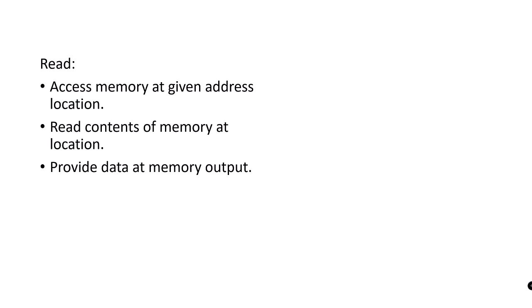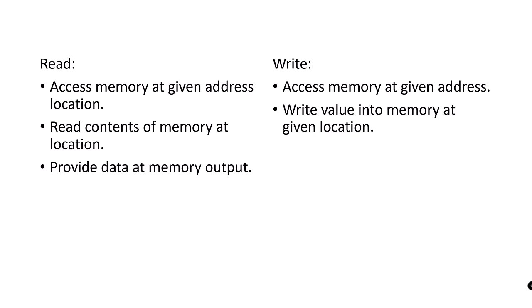A write follows a slightly different sequence. The access refers to an address in the memory device and specifies the transfer direction as write. The data to be written is provided to the device. The memory device stores that data value in the access location. The memory device acknowledges the completion of the write operation at the interface.